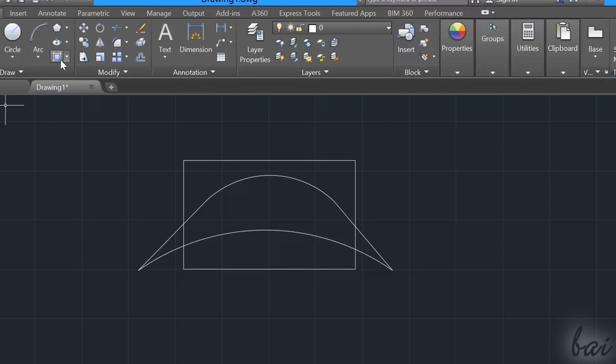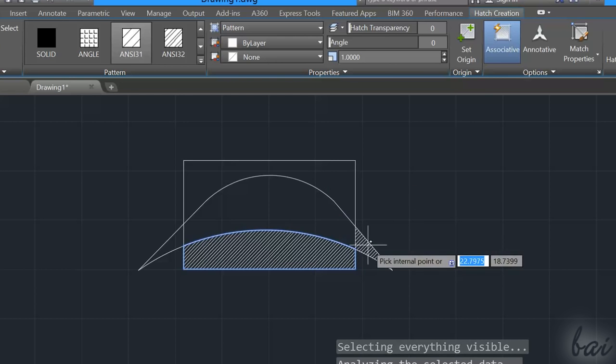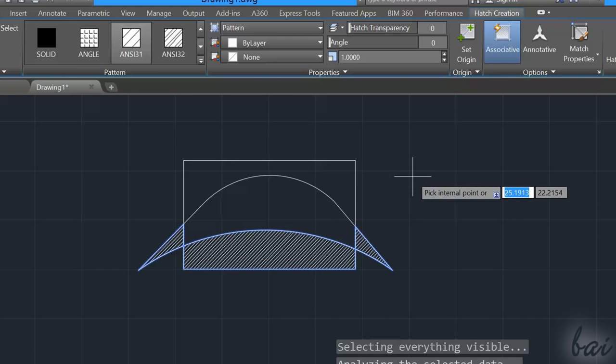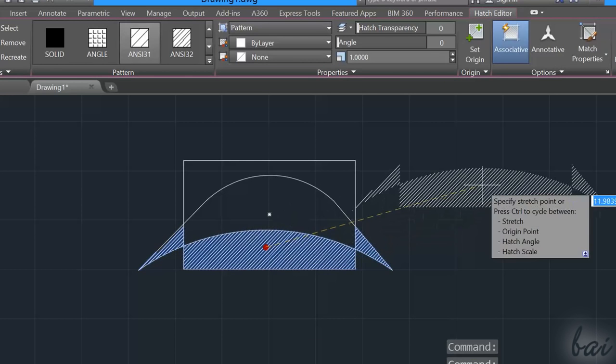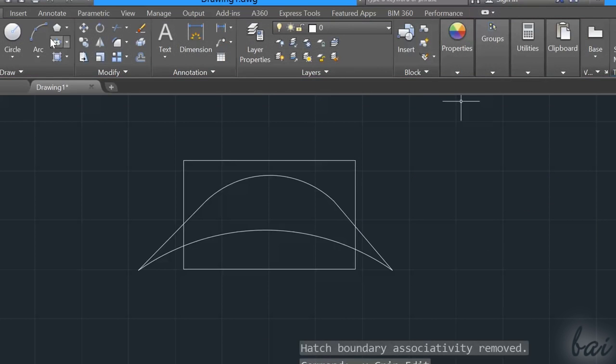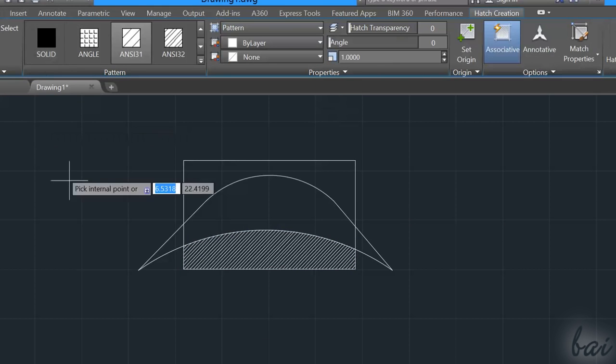The hatch commands create a unique filling every time. If you enable once the Hatch tool and create fillings that are even not linked, you will get a unique overall filling when you finish with the Enter key. If you want to create independent fillings, you must enable the Hatch tool multiple times, filling objects separately each time.